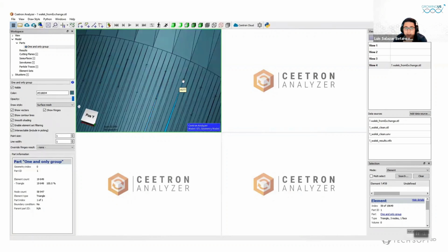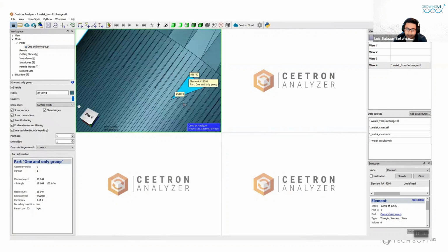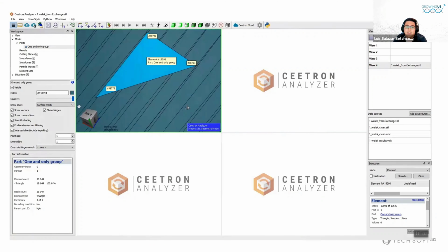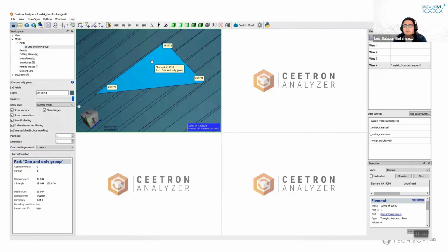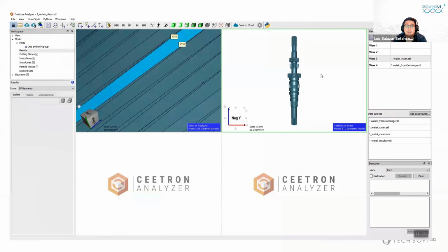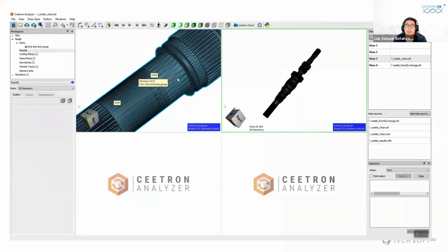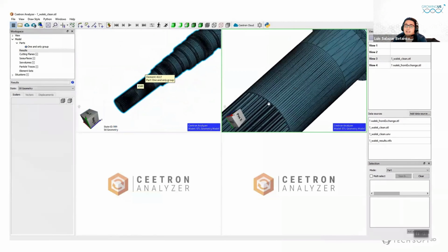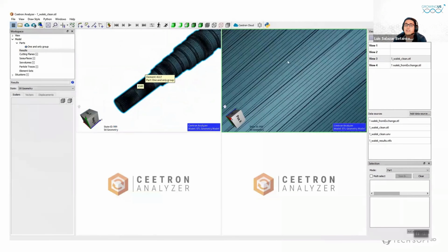So I will try to highlight exactly the overlay elements you can notice here right now. We have a face that is overlaying other faces that happens when there are some internal faces, or maybe when there are some junctions or other parts. But what we will do, thanks, we have Polygonica. So let's use that part and let's import it into Polygonica and let's just heal it. Polygonica will do a really nice job removing all these artifacts.